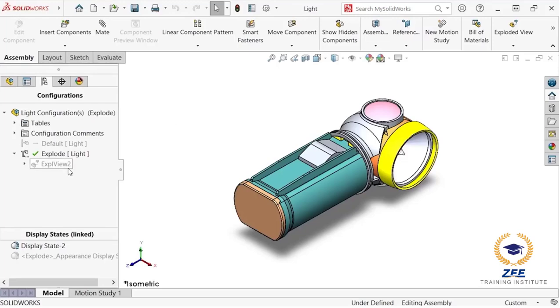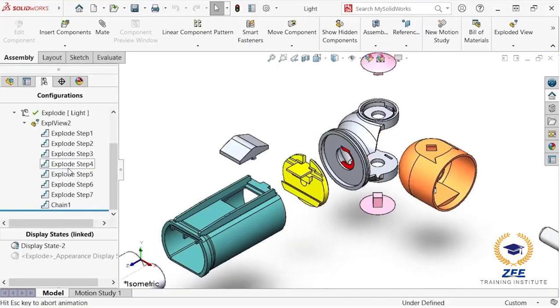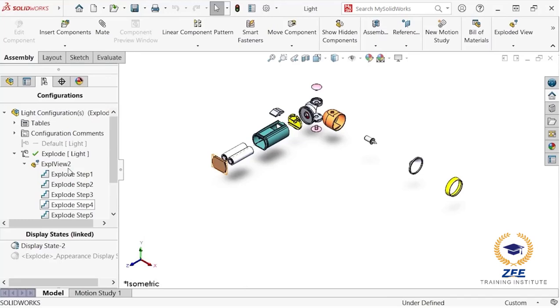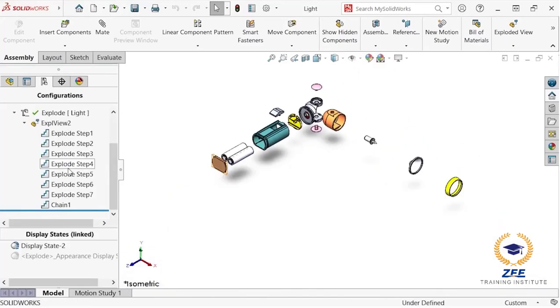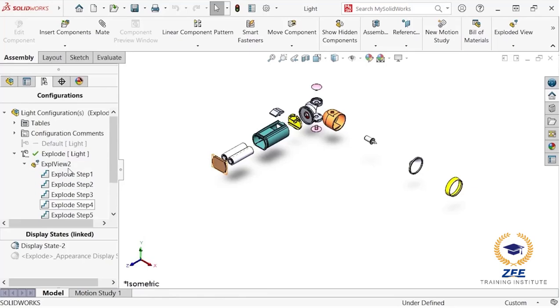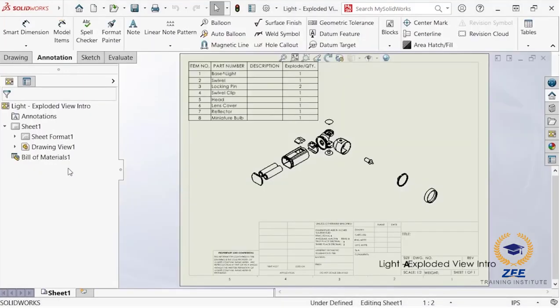You can create exploded views of assemblies by repositioning the parts component by component until the exploded view looks exactly how you want it. Once you have created an exploded view, you can then toggle back and forth between normal and exploded states. You can also edit the view at any time or use it within a drawing.